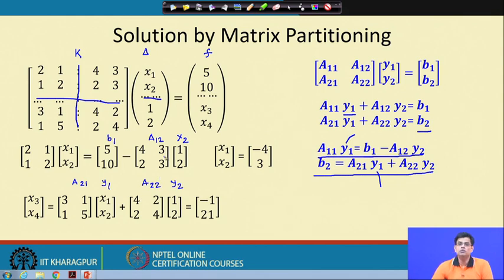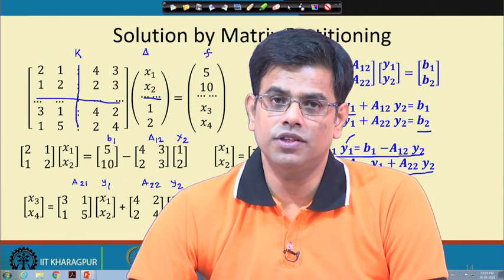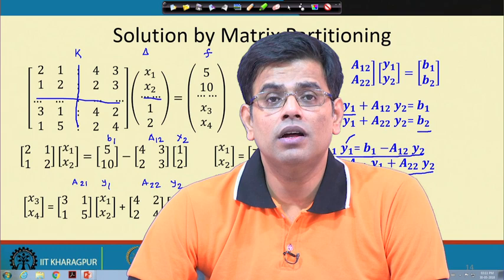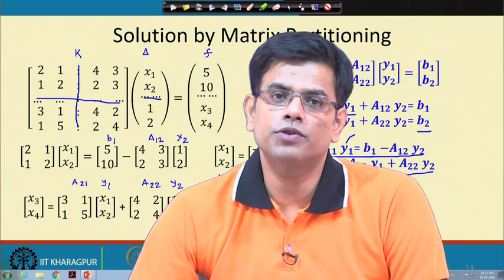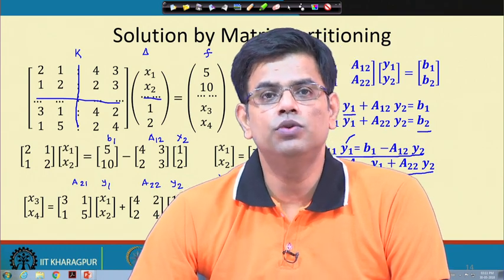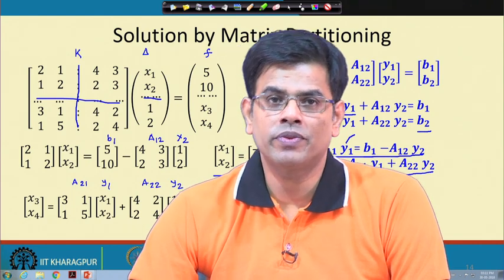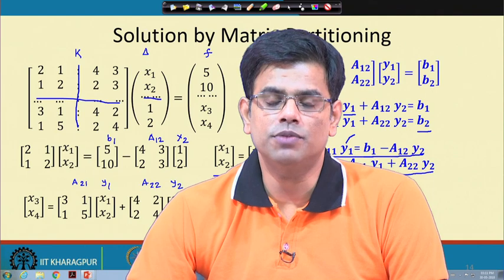This technique is worth remembering because we will be using it in this course, and this is how we actually implement the boundary condition in the system matrix or the stiffness matrix. When we learn specific problems or specific structural types, we will use this kind of partitioning to solve our system and find the unknown displacements.